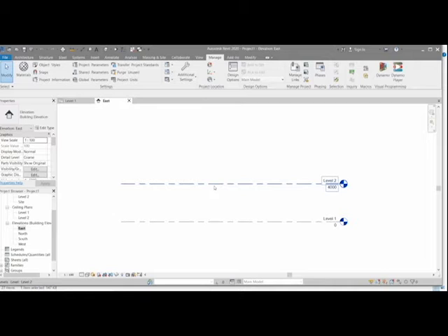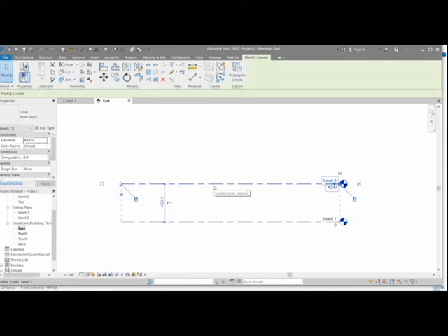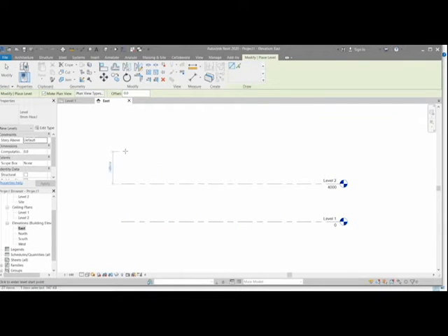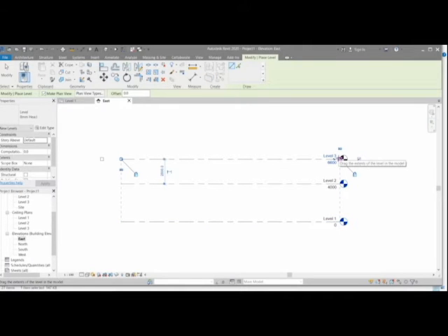So let's create a new level. To do that, I click on a level. To select it, right-click on it and click on Create Similar. I move my mouse until it snapped to the endpoints of existing levels, so they are locked together. I click and move my mouse to the other end until it snaps with the other ends of levels and then click to finish.